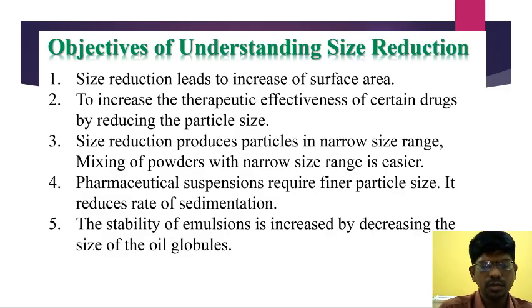Size reduction also produces particles in a narrow size range, and the stability of suspensions and emulsions greatly depends upon the particle size of the globules or particles. In suspensions, the rate of sedimentation largely depends upon the particle size, and in emulsions, the cracking and creaming stability aspects relate to the size of the globules. If you can control or reduce the particle size, there are more chances to increase the stability of suspensions and emulsions.